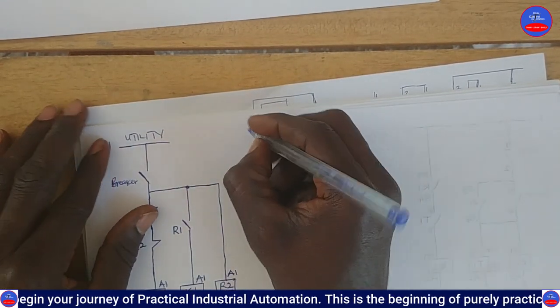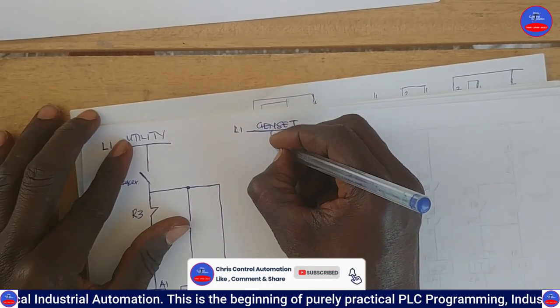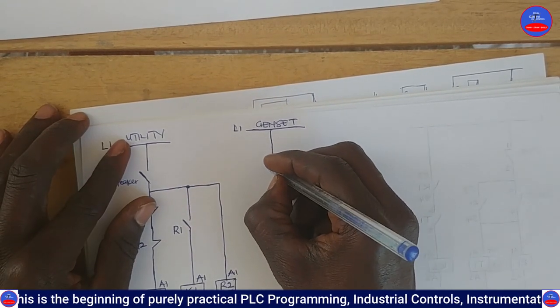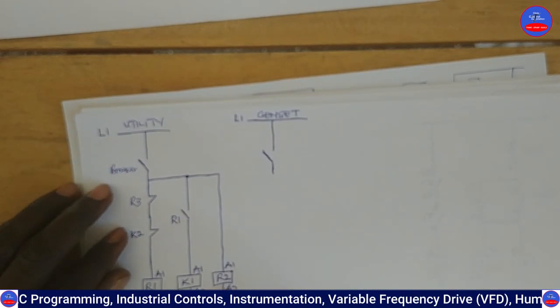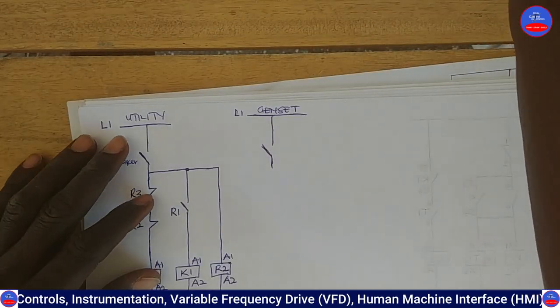This is also line 1. So you tap from here, we give it also to the breaker. From the breaker, it will go to this R2 normally close contact here.